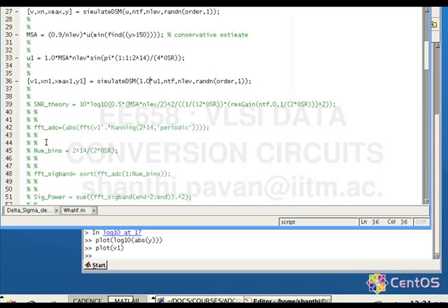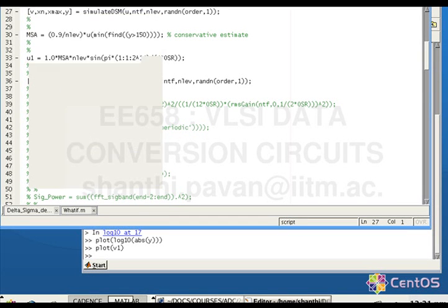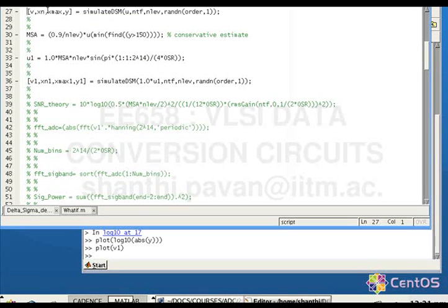Why don't we just use Xmax there, because the command will directly give you Xmax, the max, and it will give you the correct... no, it will give you Xmax with... oh, by the way, before I run away, this Xmax here, the toolbox will give you the output V, the input to the quantizer Y, and Xn stands for the state variables, for all the state variables inside the filter. If you have an nth order filter, there will be n state variables. It will give you all those state variables.